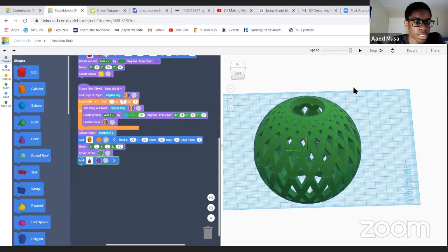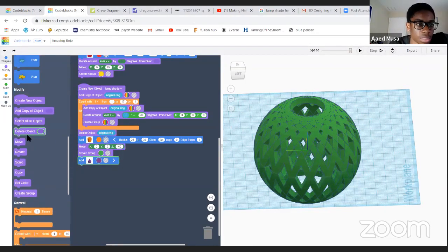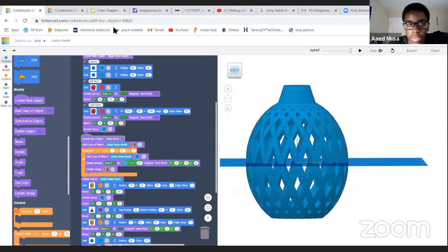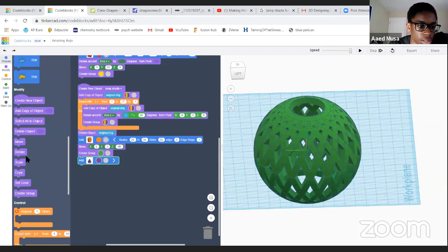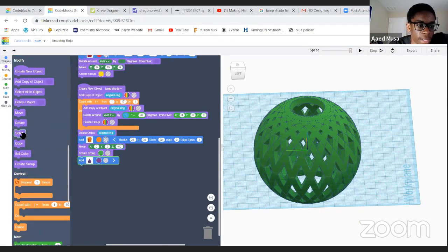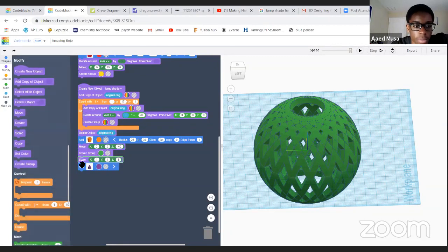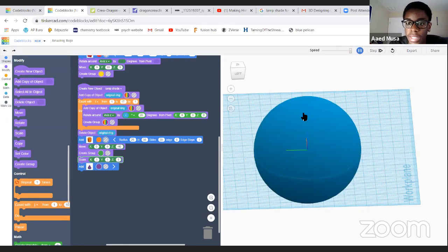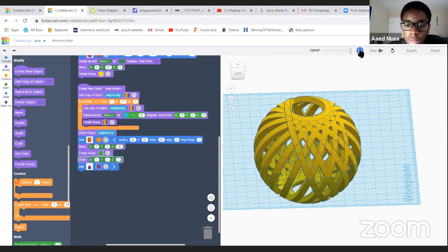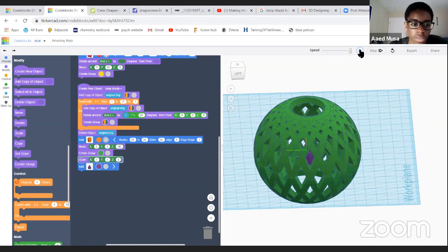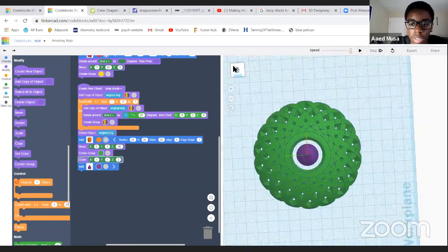And actually what Karthik had said before is we should scale our object if we wanted to get it thinner like this one. So that's what we're actually gonna do first. So I'm gonna go to modify, and where it says scale, I'm gonna drag out scale. I'm gonna actually put it before the cone. So under create group and above add cone. So we're gonna have the scale right here. And if we were to go ahead and play this, the scale does nothing to our model because all the numbers are 1.